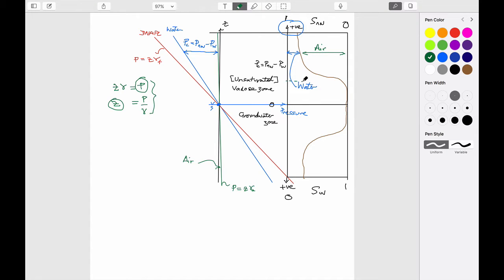And if you do that, then you have a tension saturated zone that we talked about last time, which is this area here where it's below the bubbling pressure, PC0, which is the pressure at which a bubble of air can get into it. The water's in slight tension. And above that, air can get into it in progressively larger and larger volumes as it desaturates. So it goes into the largest possible pore here first, and then it starts filling up the smaller and smaller pores that are connected in the system here. And that's exactly congruent with the behavior below the water table.